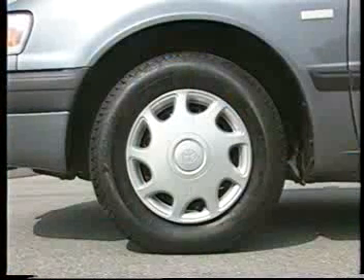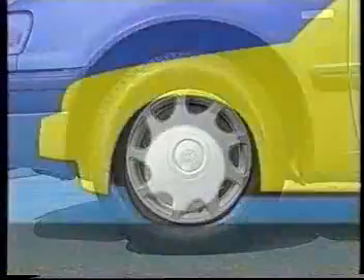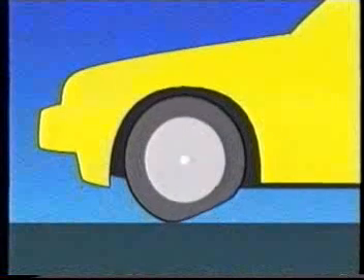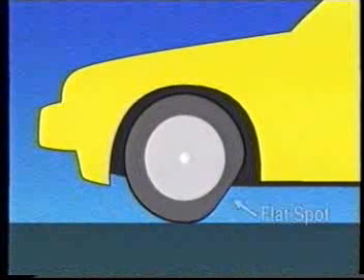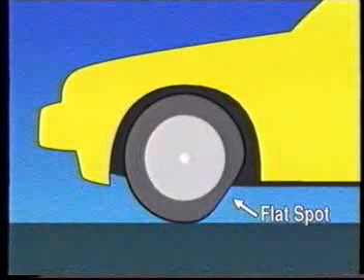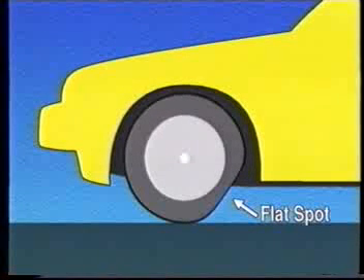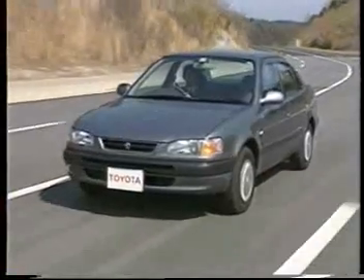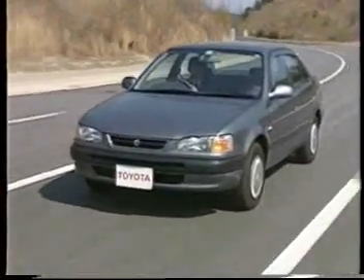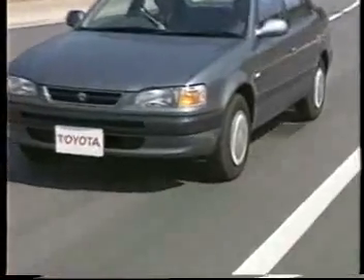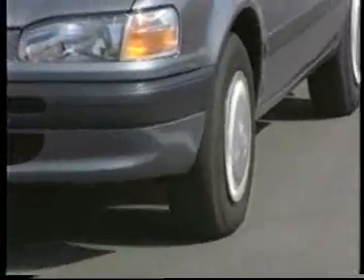Another tire imbalance problem that occasionally crops up is a flat spot. If a vehicle is parked for an extended period of time with its tires warm after driving, the portion of each tire that is in contact with the ground will become flat. In general, this problem disappears spontaneously after driving the car a little, as the tire temperature increases.